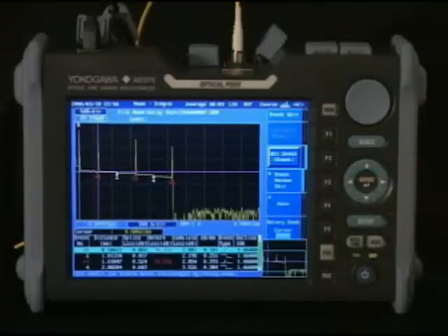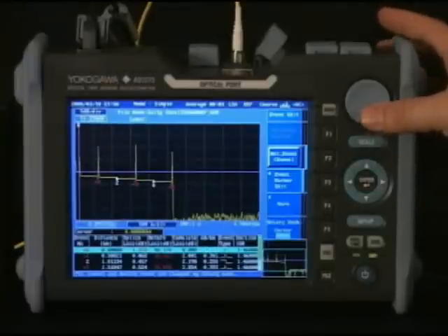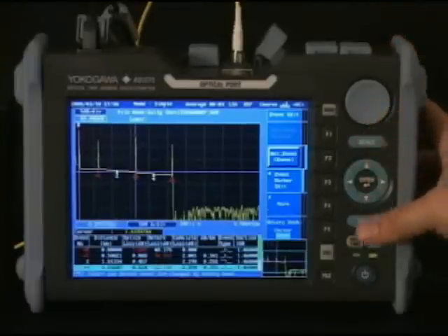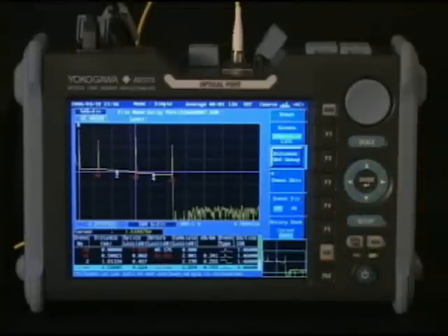Select the F5 key to change the thumbwheel away from event. Now you can move the cursor to where you want the measurement reference and set it. Zooming allows you to get a more accurate placement on the trace.